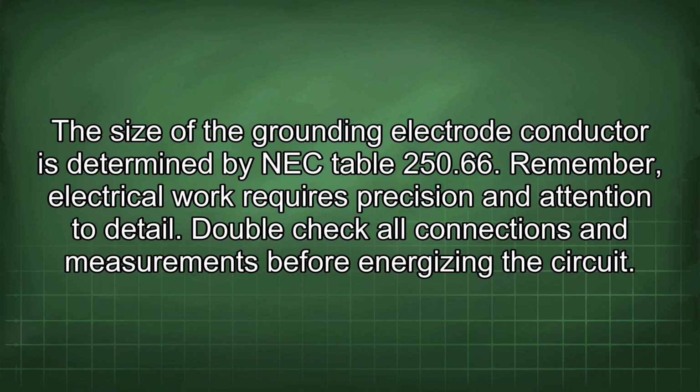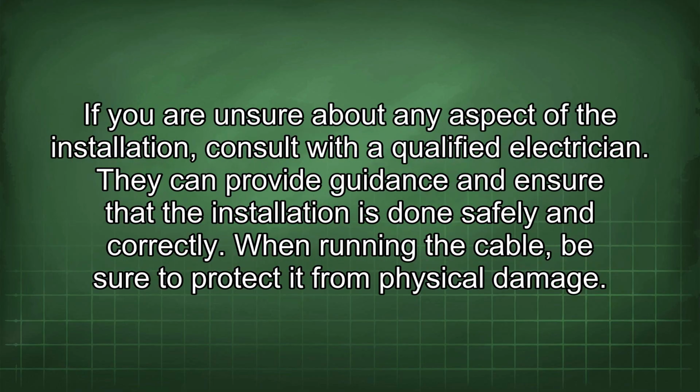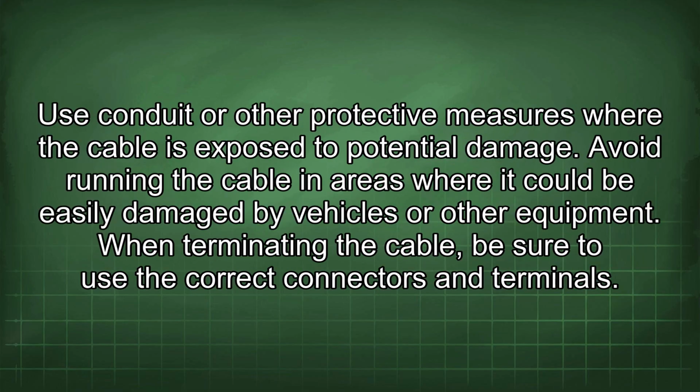Remember, electrical work requires precision and attention to detail. Double-check all connections and measurements before energizing the circuit. If you are unsure about any aspect of the installation, consult with a qualified electrician. They can provide guidance and ensure that the installation is done safely and correctly. When running the cable, be sure to protect it from physical damage. Use conduit or other protective measures where the cable is exposed to potential damage. Avoid running the cable in areas where it could be easily damaged by vehicles or other equipment.